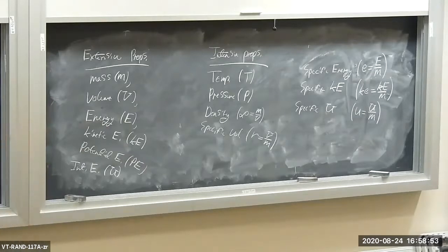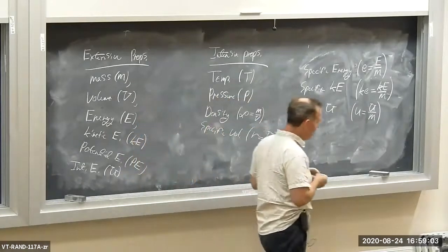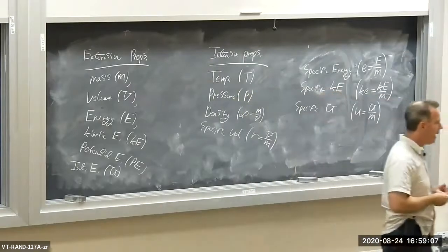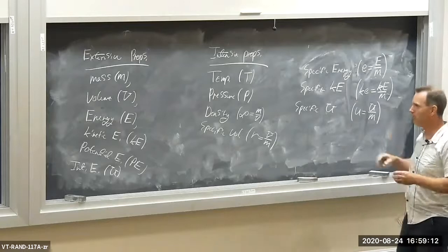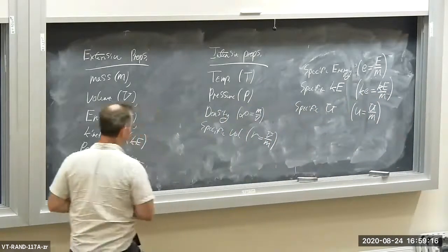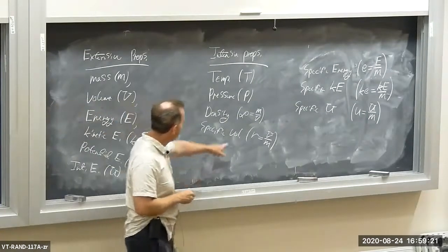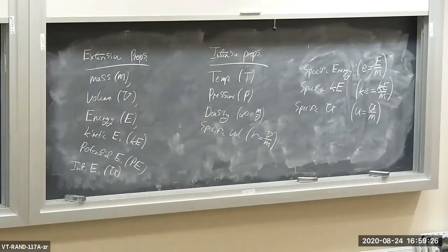All right, so we have intensive, extensive, and how to convert between the two. We got some nomenclature here. Usually the extensive properties, with the exception of mass m, are uppercase, and typically intensive properties, especially the specific quantities, are all lowercase. Density is a Greek letter, that doesn't count. Pressure and temperature are exceptions. Everything else is lowercase. Okay?